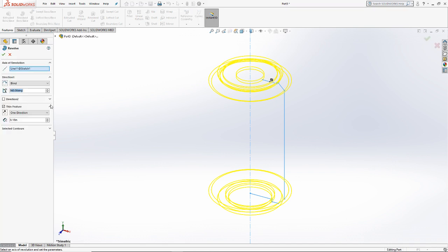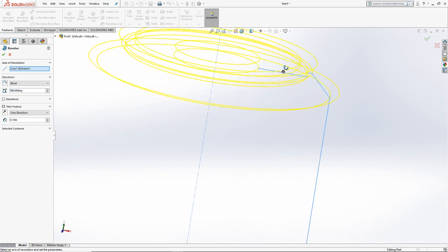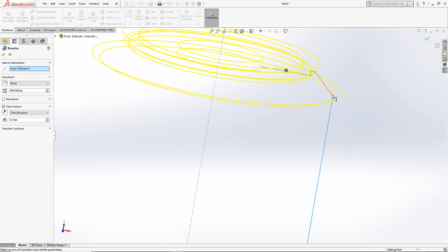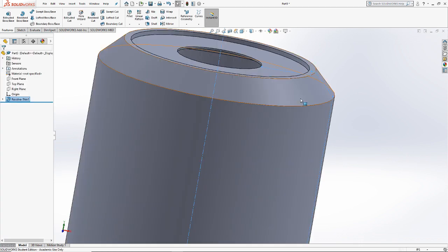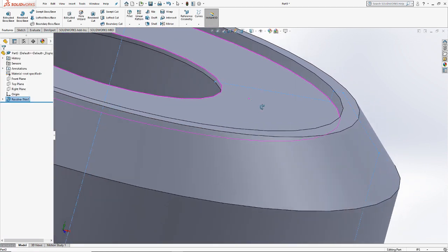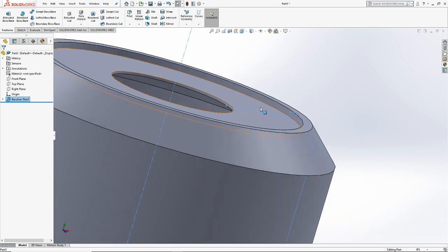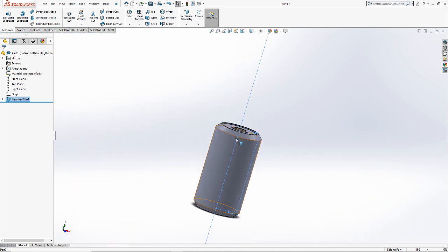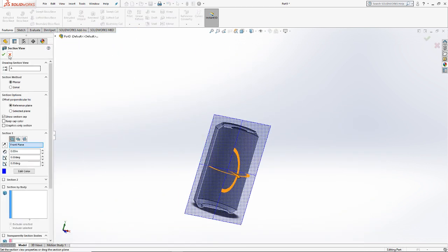And it says, okay, well, if you're only extruding a line, I'm going to use something called a thin feature in the extrusion. So now it's going to extrude material that is thin around the center of the line. So if I created something that had a thickness here of 0.2 inches, for example, and then accepted it, what it does is create that thin material offset from the line. So it might be easier to see if I establish a cross-sectional view here.